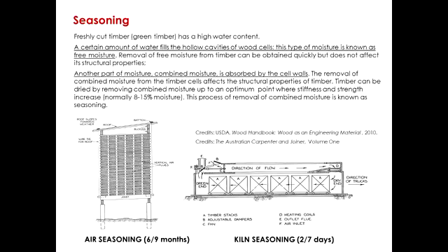And that's why we get into seasoning. Seasoning is a very important process because you cannot use freshly cut timber. What happens is that there is a high amount of moisture inside the hollow cells of the timber products. So we need to make sure that we lose that moisture, so that there is the same amount of moisture between the timber product and the natural environment that surrounds it. Okay? And that is generally between 8 and 15%, depending on where you are.